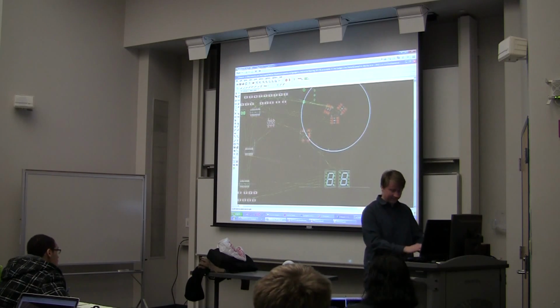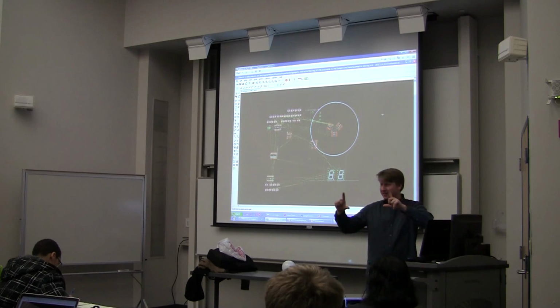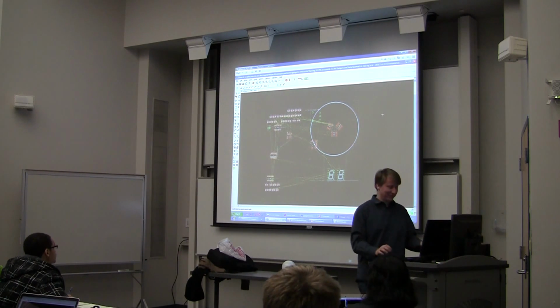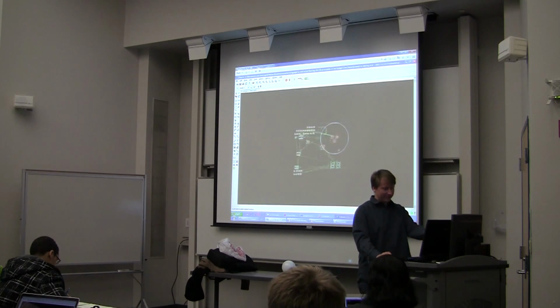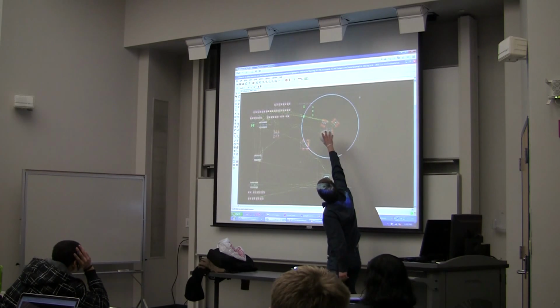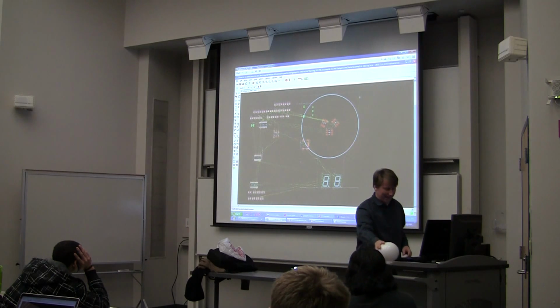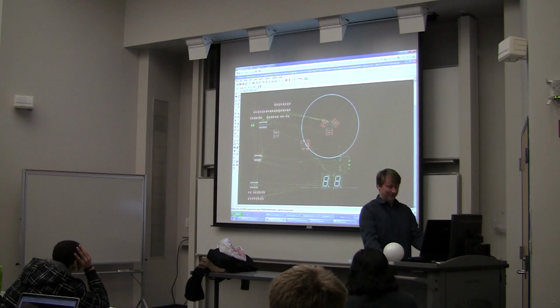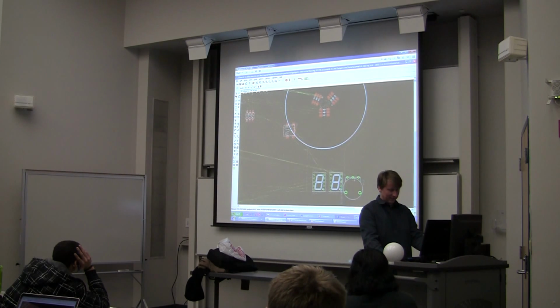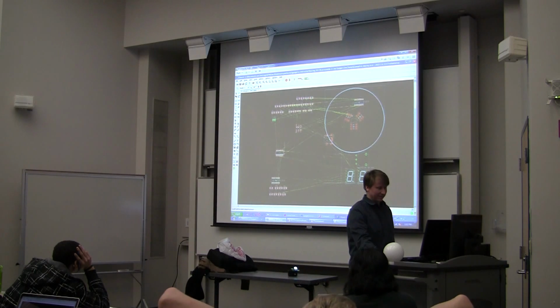Right, so you can do all kinds of funny stuff with your shape. In Eagle, it'll yell at you if you're not within your little 80 millimeter by 100 millimeter box, but you've got an 80 millimeter by 100 millimeter photo. So now you can imagine, this is the physical thing, right? I know what I want it to look like. I'm going to stick this thing over the top of that, and then there's going to be this crazy little diving board sticking out with my digits. And since I have that, maybe I'm not going to stick the potentiometer over here. I'm going to stick the potentiometer over here on my little diving board so that you can get to it. But then all of my other bits are going to go over here.